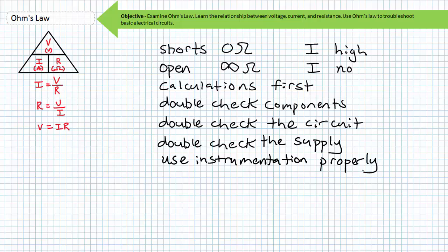If you're going to use your DMM, use it properly. We already covered the ohm meter in a previous lab practices lecture. We'll go into detail about voltmeters and ammeters real soon, but recall the basics: function, leads, range, and placement. Use the checklist. Ohm meters are never used on live circuits. They read the resistance from terminal to terminal with a device of interest removed from the circuit. Voltmeters read voltage across something. Voltage is a 2-point measurement. Ammeters read current through something. Current is a single-point measurement which must flow in and out.